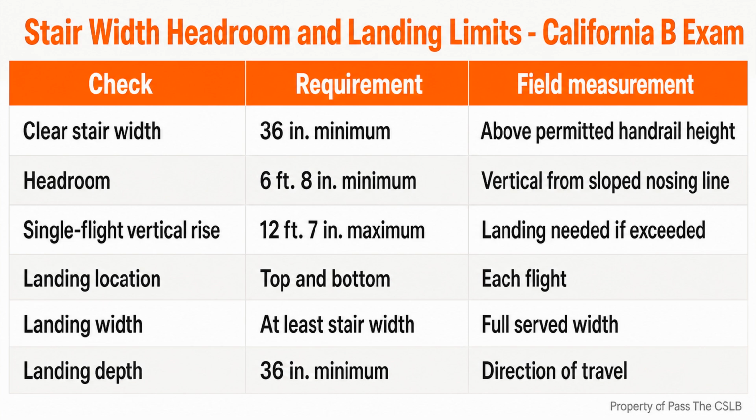That trigger is based on the number of risers, not the total drop beside the stair. A short stair can require a handrail even when no guard is required. I keep that distinction simple. Riser count triggers the handrail, open edge elevation triggers the guard.